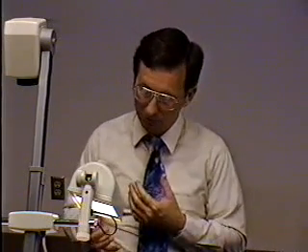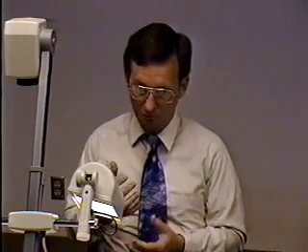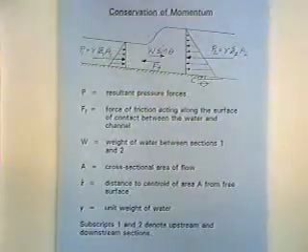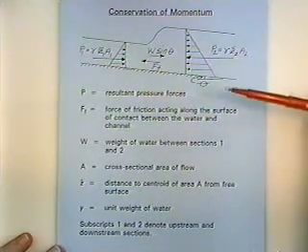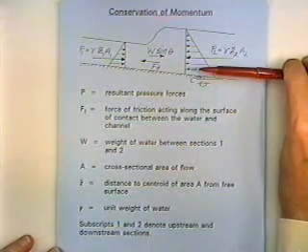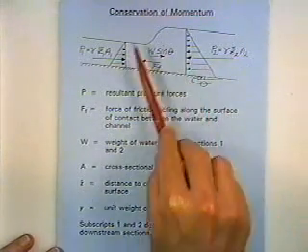it's quite obviously you can't use Manning's equation to estimate energy loss. You don't have anything to estimate energy loss. And so we're not going to try to estimate energy loss. We're going to, instead of conserving energy and looking at energy terms, work in terms of a conservation of momentum. And so basically what this page does, it defines the basic terms. And so you can read through there and look at the diagram and define basic terms.